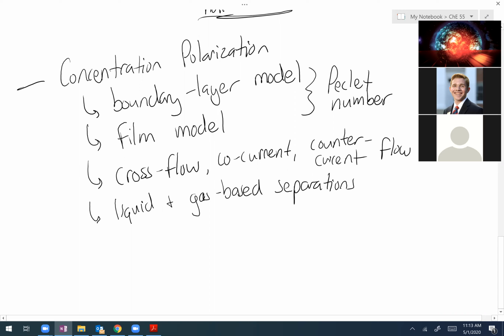You don't technically increase the effective membrane area, but the necessary area to do the separation you want will go up. Does that make sense? Yeah, is there a way you can still increase this. Well, okay. You really can actually. It just means the necessary area to obtain that stage cut will be increased, right?